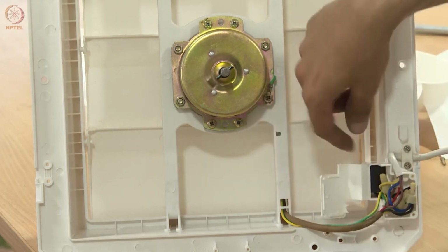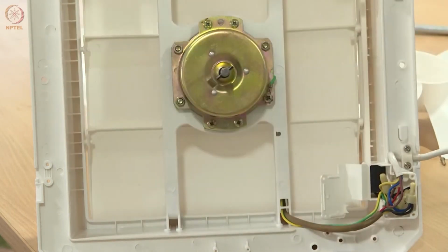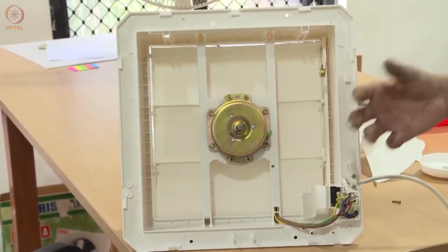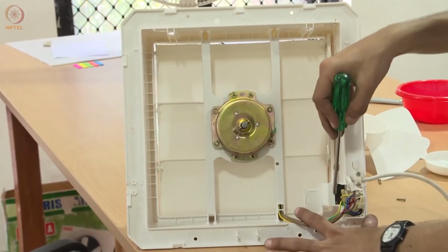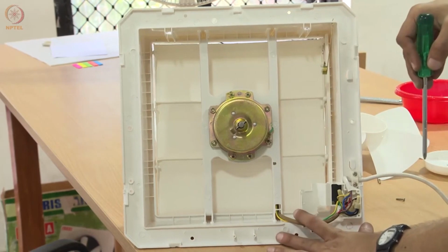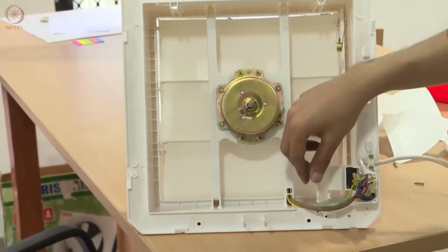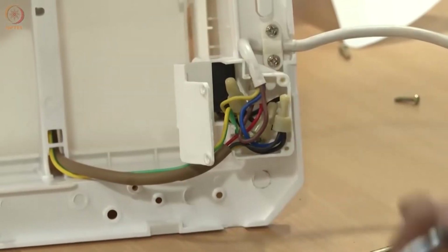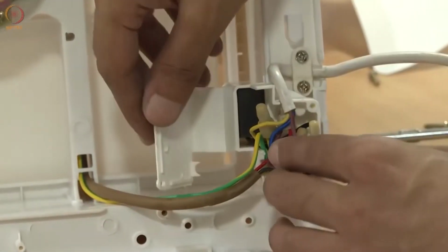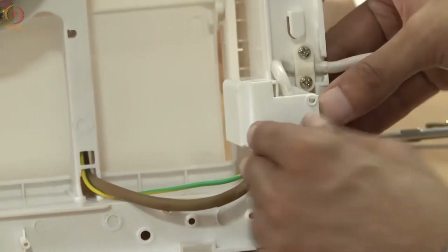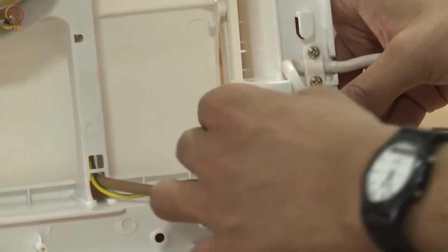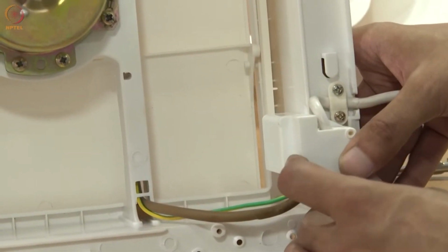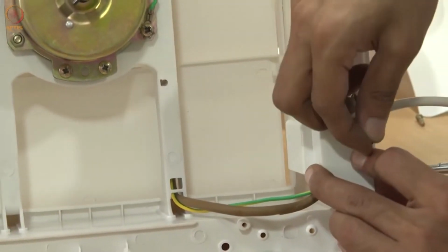This entire plastic piece, the housing of the fan, is injection molded, and this sort of mechanism we call a monolithic mechanism, and this is what we call a live hinge. Live hinges help us eliminate a revolute joint, and just by deformation of the plastic itself at a very narrow point, you get a very good revolute joint without the use of an additional pin or other complicated mechanical arrangements. So let me just put it together.